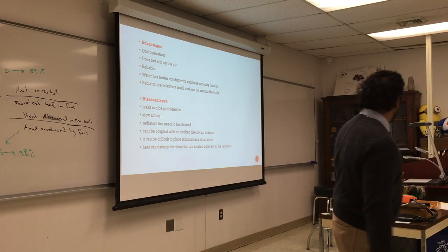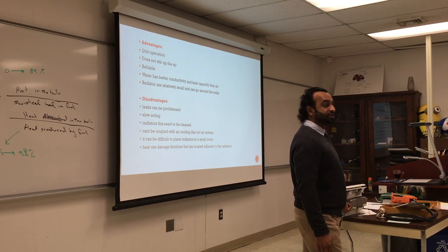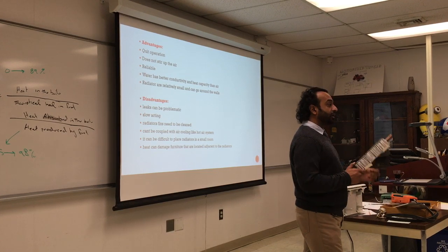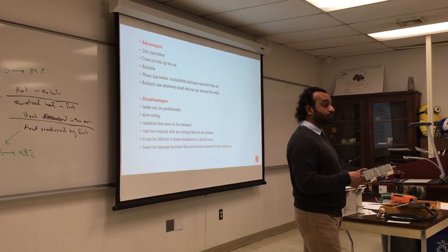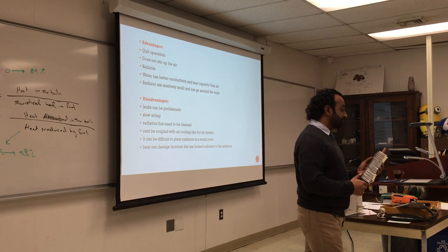So, these have to be cleaned periodically, like once a year, depending on the situation, how much dust or animal hair you have. Because if this gets clogged, the air is not going to flow around them. And Chris was saying, like, what if it's too much heat?